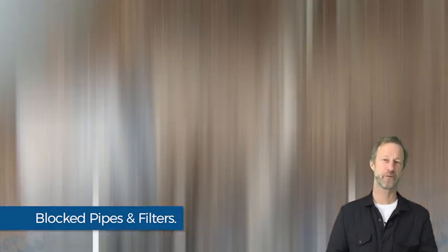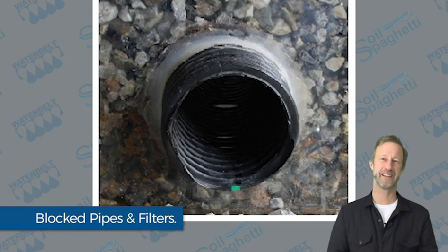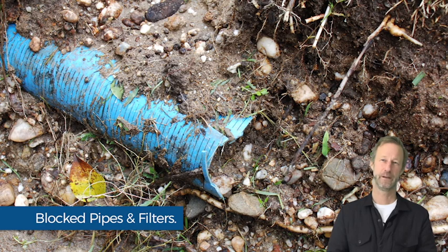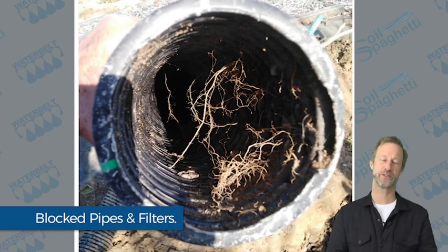It creates a reservoir into which soil particles can settle and may delay the buildup in the pipe, but it also creates a flow channel for water. As shown earlier, the water will flow to the lowest point, which is the bottom of the drain rock, and it will simply flow through the drain rock without going into the pipe. The flow will also wash soil particles down into the large spaces between the rock aggregate, completely blocking it in a short time. Plant roots growing through the slots are also a common blockage problem.